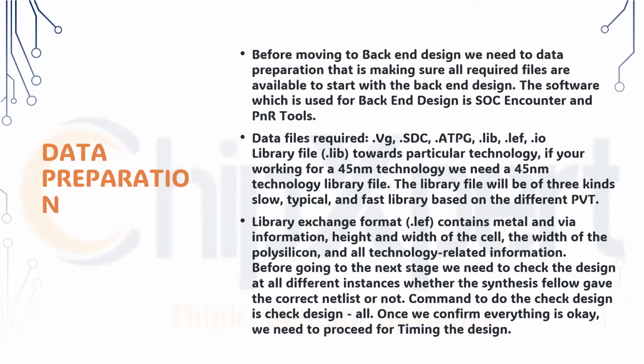That will be defined according to the PVT conditions, that is the process, voltage and temperature variations. Process is like the fabrication process, how the quality of the process is going. Voltage variations are due to the heat or the input voltage, and temperature is how the temperature behaves outside of the chip. That will vary for each of the standard cells and their behavior.